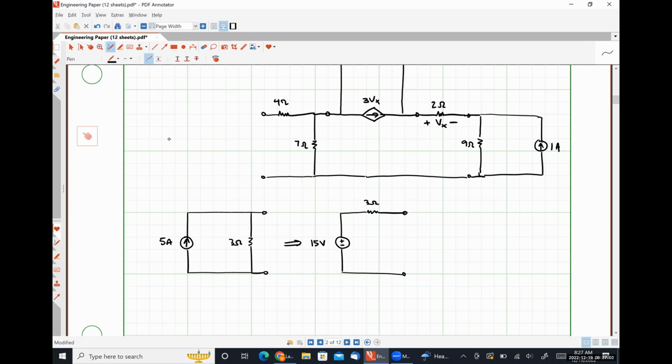that practical current source, and in its place, I put in my transformed voltage source. So what did that do? Did a couple of things, okay? Number one, it introduced a node, arguably bad. It eliminated a mesh, arguably good.